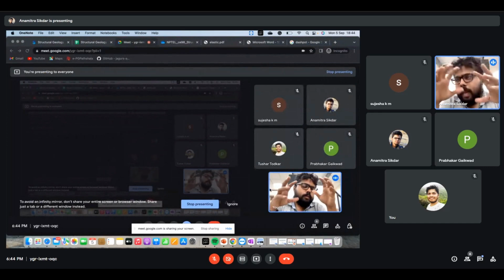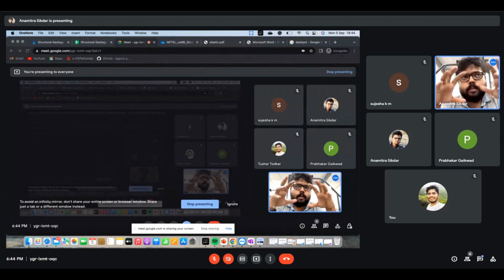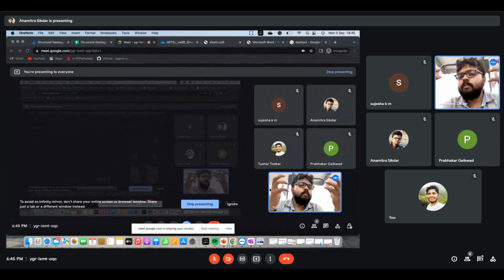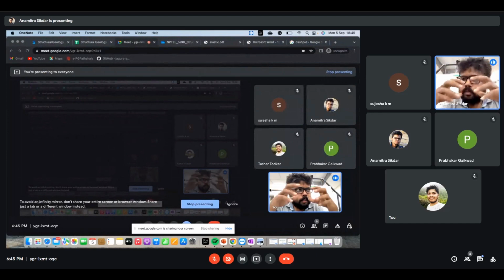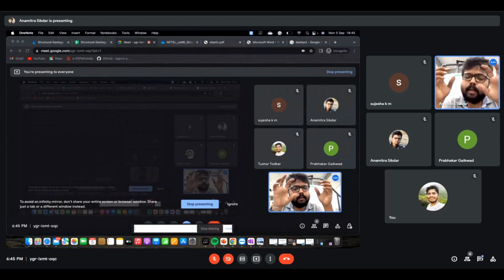So you have a grain, you apply stress, the dislocation entanglement happens, and after that new grains form. Whenever new grains are forming, we call it recrystallization. That's why if you have a big grain and recrystallization, the grain size will reduce, right?